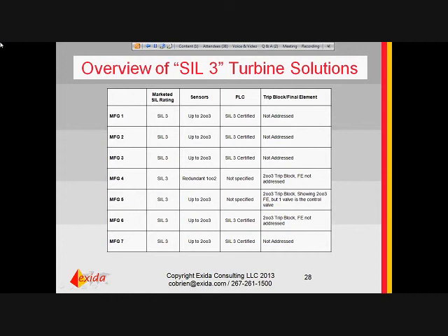So there's an issue there with sharing equipment. Typically in a turbine application, say for overspeed, failure of the control loop can cause the hazard. So including the control valve and the protective function without some additional calculations is optimistic.